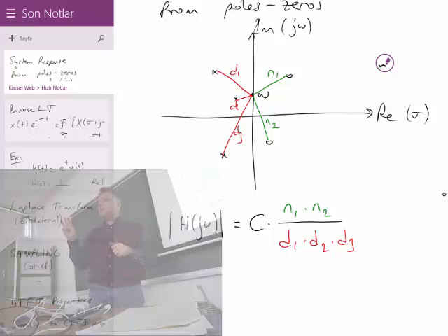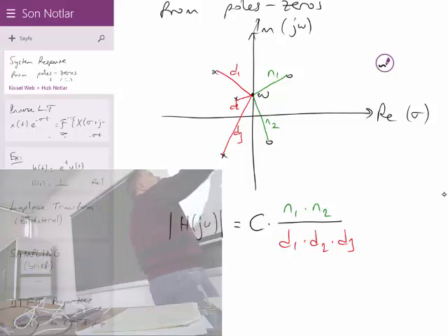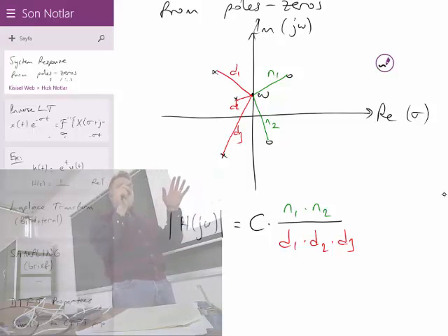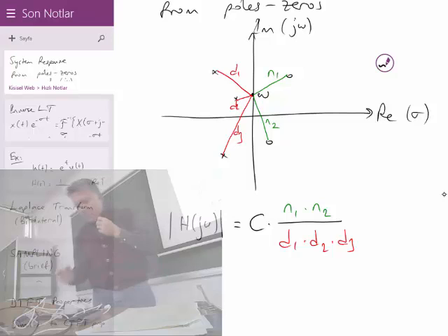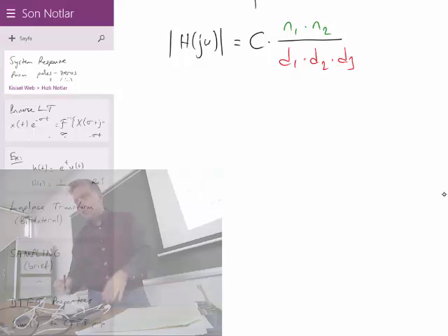That applet, this is the third time I'm referring to it, was a very versatile and useful tool to design filters as well, because whenever you insert poles and zeros, by dragging that omega upward or downward, it was tracing the magnitude of H of j omega, and you were designing the filter. By insertion of a different zero, you may make it a sharper low-pass filter sometimes, or a poorer low-pass filter. Let's make it a band-pass, band-reject filter. You were just inserting poles and zeros for that. But you may guess that making a low-pass filter could be something like this.